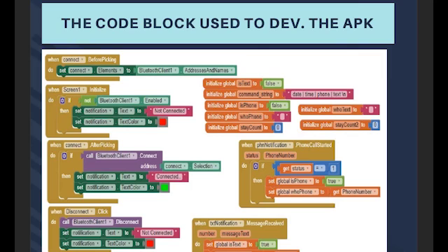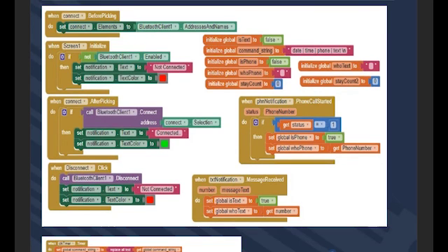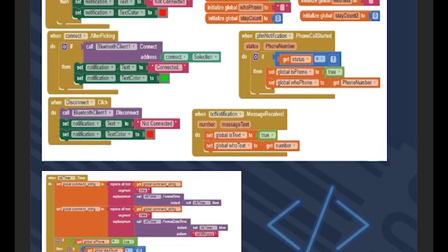In this project, when the Bluetooth client is connected, it means that the transmitting circuit is actually connected to the phone, and when it is not connected, it means that the transmitting device is either not connected or we have forcefully disconnected it. And so when it is connected, we give the phone notifications, we give the text notifications if there are any, and this would be transmitted in the form of a string of date, bar, time, bar, phone, bar, text.